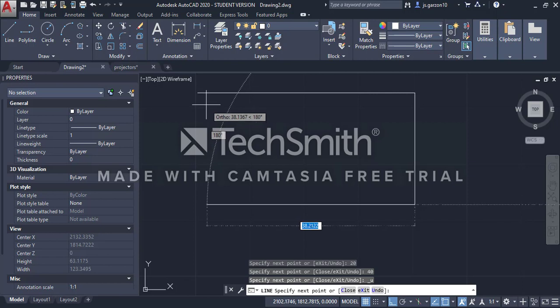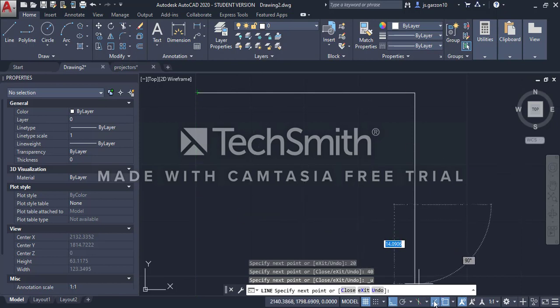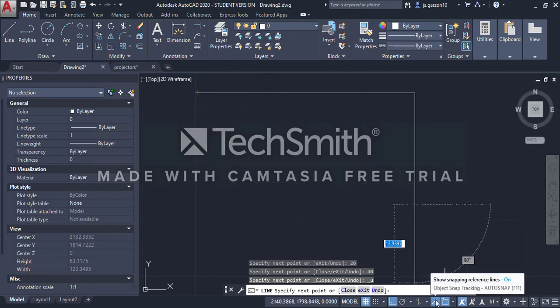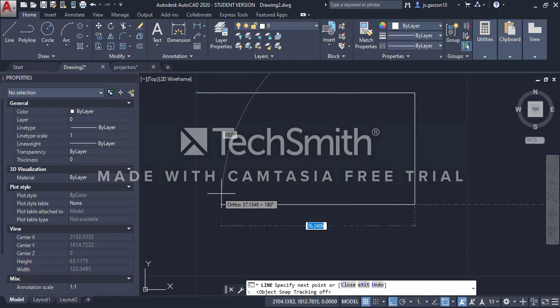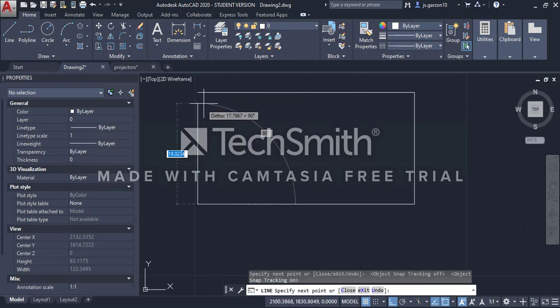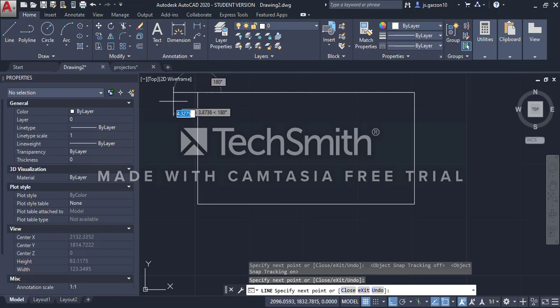So if you want to be sure that you close properly the drawing, you can just simply locate your cursor in the end point and it will automatically snap you to this side if you have on this option. If you don't want this, you can simply turn it off or zoom in and zoom out. When you have finished, you can just press enter.